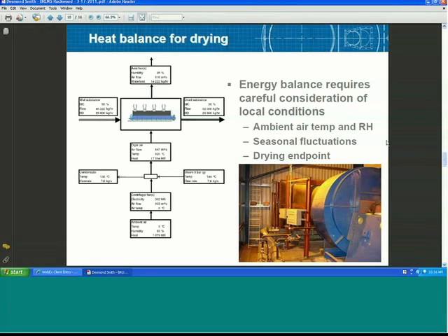The photograph is of this Norwegian district heat system, which has a hot water heat exchanger taking ambient air and running it through this ID fan, which drives the air pressure from below the mat, through the material, doing the drying. These conditions vary greatly depending on your ambient air temperature, and there's a summer and winter min-max situation that we have to consider when we size these things, and it can be quite a drain on the process. That was a very big concern for our co-firing power plant. Next slide, please.